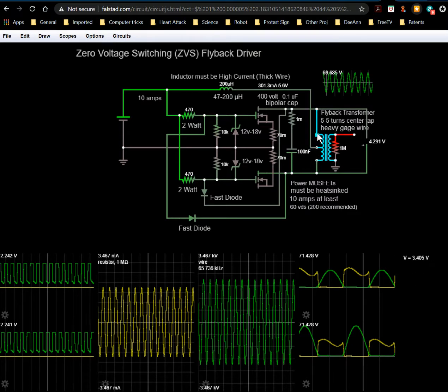Basically, the voltage it forms to try to maintain that current tends to be the opposite of what was impressed across it. So it won't be positive here and negative here, which is how we charge the field up in our hypothetical coil, but negative here and positive here, so it actually reverses it. And that's key to understanding the oscillation in a tank circuit, because that's what happens. This field collapses, okay? We have charged it up with a positive here and a negative here. Again, ignore this middle thing for this discussion. But basically, that charges this capacitor up with a positive here and a negative here.